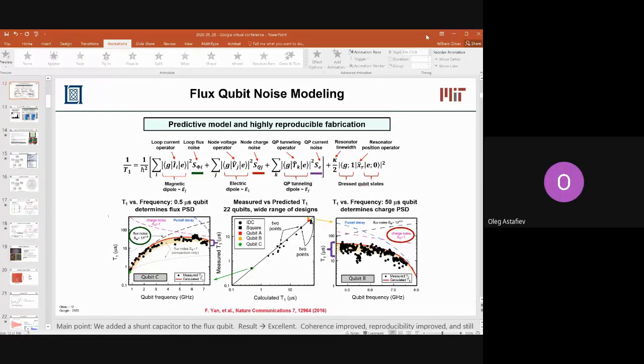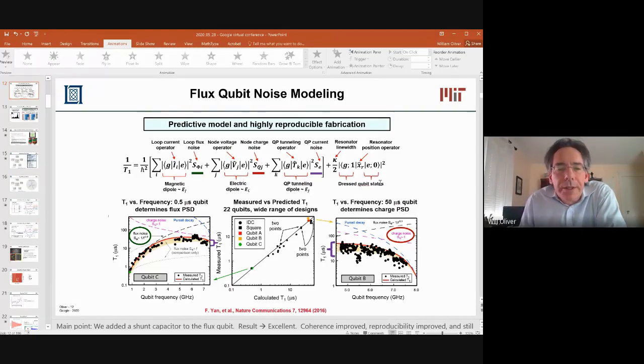Yes, okay. So you demonstrated these long times for the shunted flux qubit, but my question is, do you still have some bad qubits or good qubits? You demonstrated this maybe for the best ones, and what is the scattering of parameters, or scattering of times, depending on qubits? Yeah, so what I want to emphasize in this middle plot here is that we intentionally varied the parameters over a wide range. If you look in the upper right corner here, these 4 qubits were basically identical to one another. And so this gives you an idea of the fluctuation in the coherence times that we measured. And then, of course, it's impacted by the quasiparticles. And so we have to pump those away to make some statement about the underlying temporal variation due to other mechanisms besides quasiparticles, et cetera.